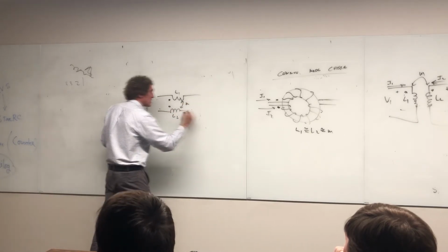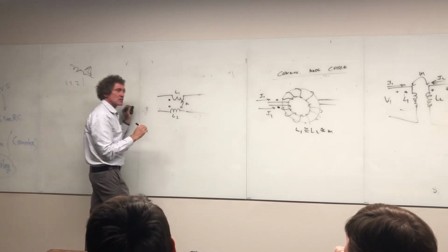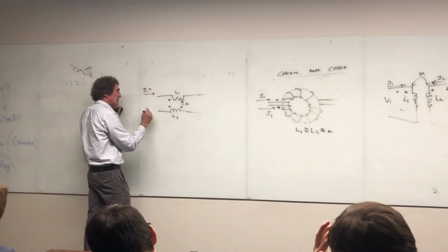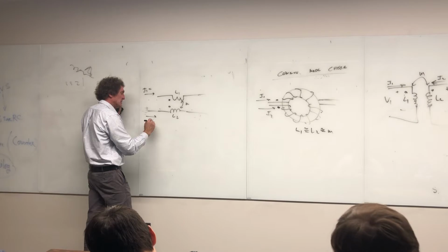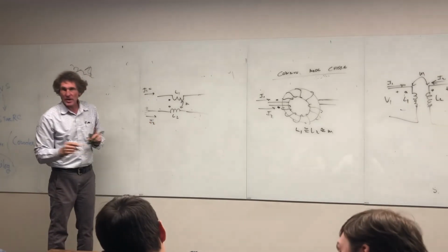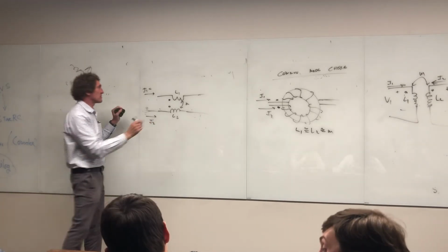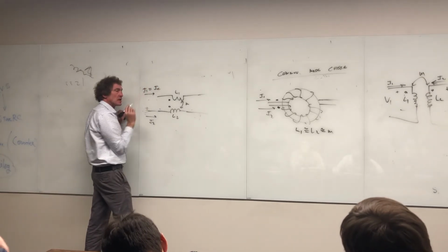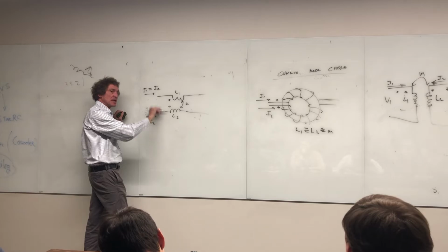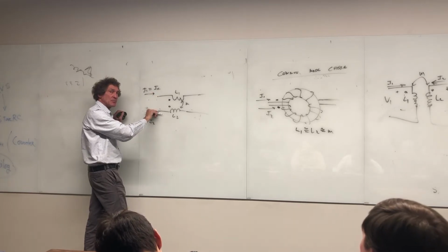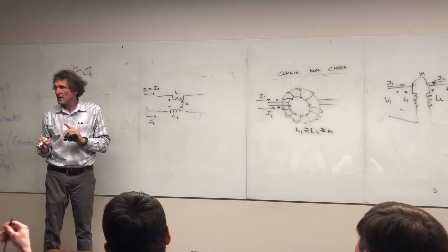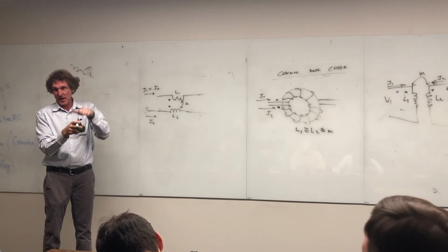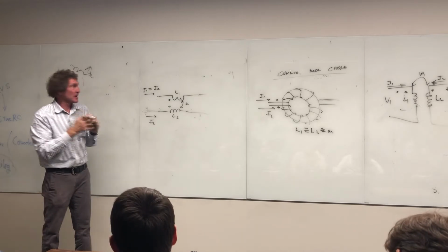Now, here, you can say that that goes to a device, and we're going to have a current I1 here, and we're going to have a current I2 here. Keep an eye on this. Now, I1, I'm going to say, is defined as something called a common mode current. That's I common. Common mode means the current's the same direction, same magnitude in both. Do y'all follow me in this class? Common mode means it's just the same, it's common. The same exact current flows in the same exact direction.